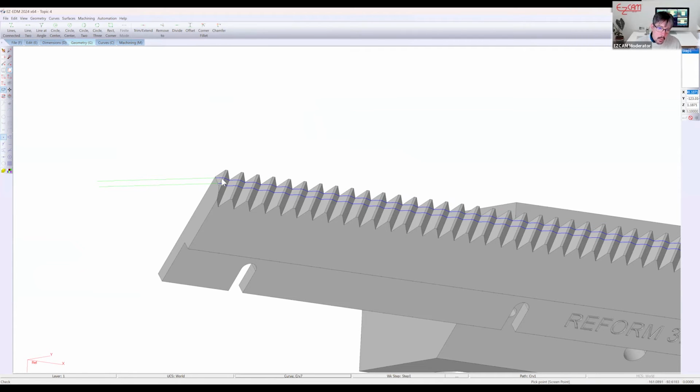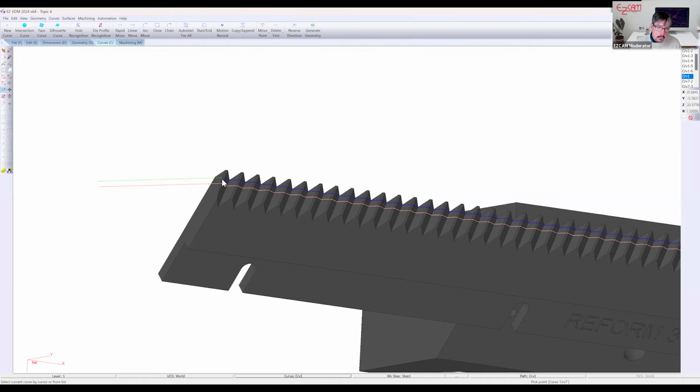Now I don't want to double up on this. I don't want to have like a line going and stopping here and then going here. It's going to affect our path. So I'll just go in, change delete from and to delete first, delete last. Okay, now we'll pick the next curve, do the same thing, delete last, delete first. So now we're going to build a linear line, snap to all, change curves.